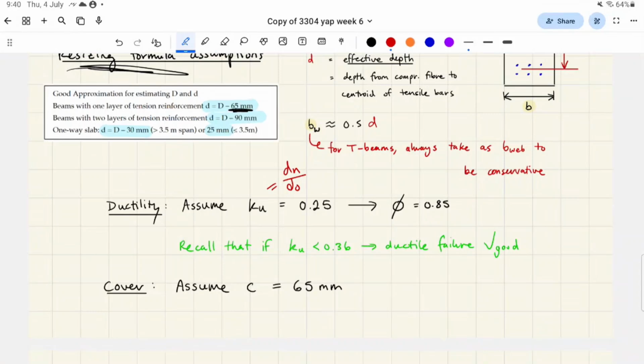If the concrete completely fails first, it's not good because the Play-Doh is going to break brutally, essentially. But if the Play-Doh yields first, it's going to provide a bit of that yielding strength. Okay, this analogy is starting to break apart, but hopefully you get what I mean. You want the steel to yield before the concrete, essentially, and it's to do with how low this ratio is.